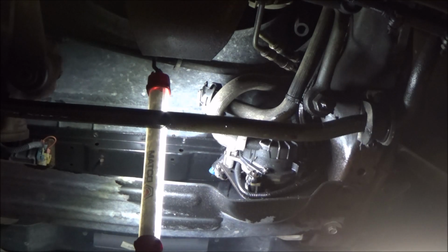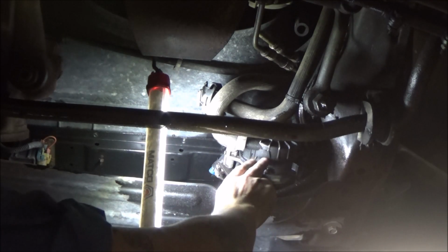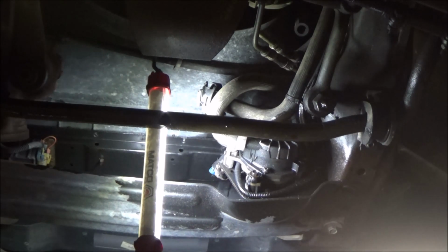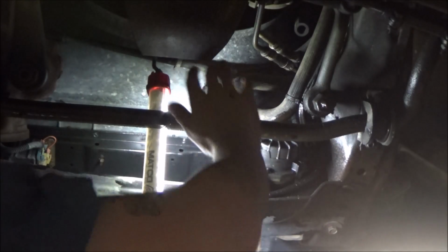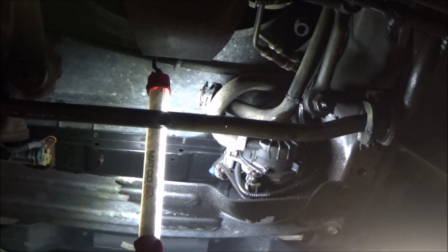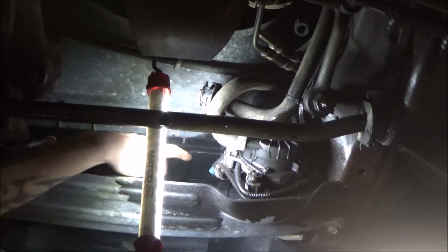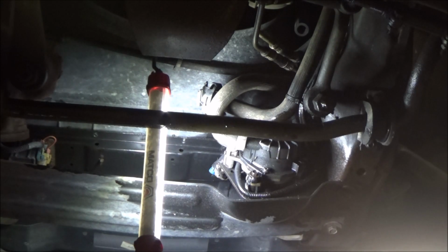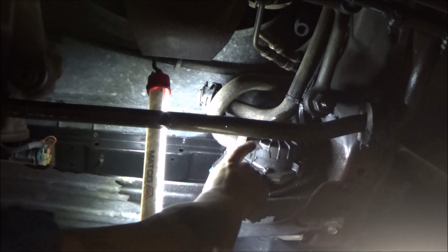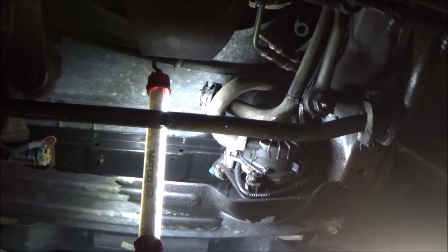This air pump solenoid controls airflow from the air pump itself into the exhaust manifold. That's basically all it does, is it opens this valve here and allows airflow from the motor to come up through this valve and then to the exhaust manifold. This motor should still run, guys, even if we did have some sort of solenoid fault. The motor would still run, but we would still have this P0410 fault code because our oxygen sensors would not be going lean. We would not have airflow into the exhaust manifold. So we definitely need to be worried about this motor at this point, guys. We know for a fact we have a bad solenoid. So let's start attacking this motor.